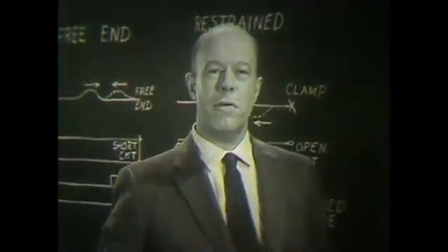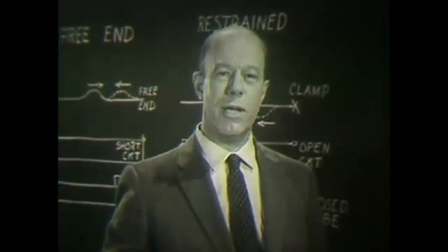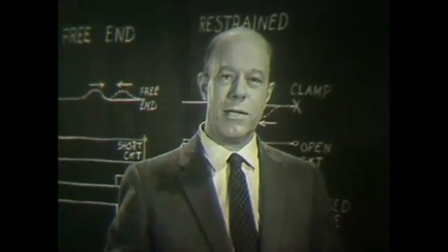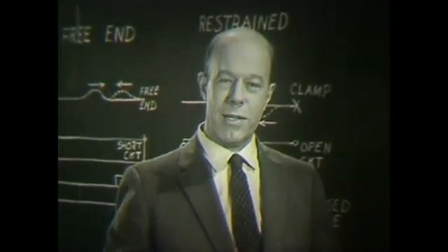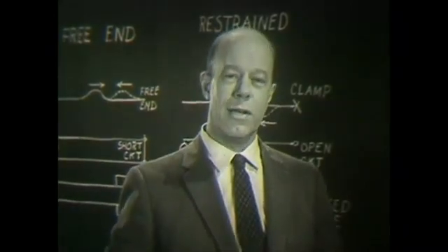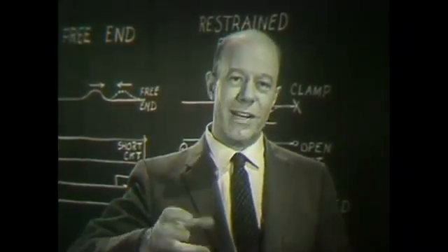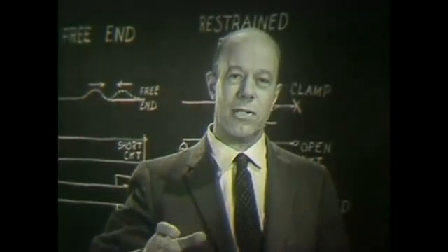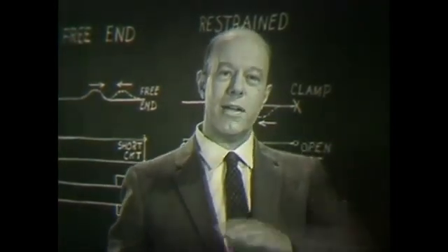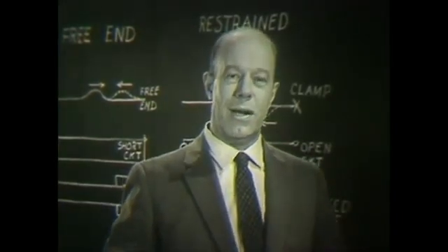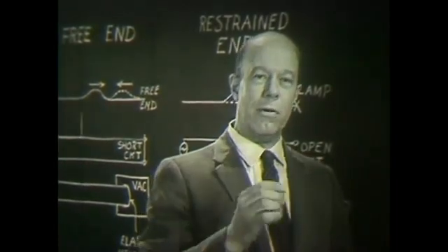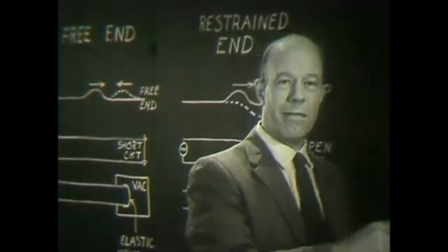You're probably most familiar with the term impedance through your studies in the field of electricity. But this impedance concept is just as applicable to wave systems of other kinds as well. On our mechanical wave machine there, for instance, the cause of the waves is the oscillating torque which I apply to the first cross arm, and the result is the oscillating angular velocity imparted to the medium. On that structure then, the impedance, the mechanical impedance, is the ratio of the applied torque to the resulting angular velocity.